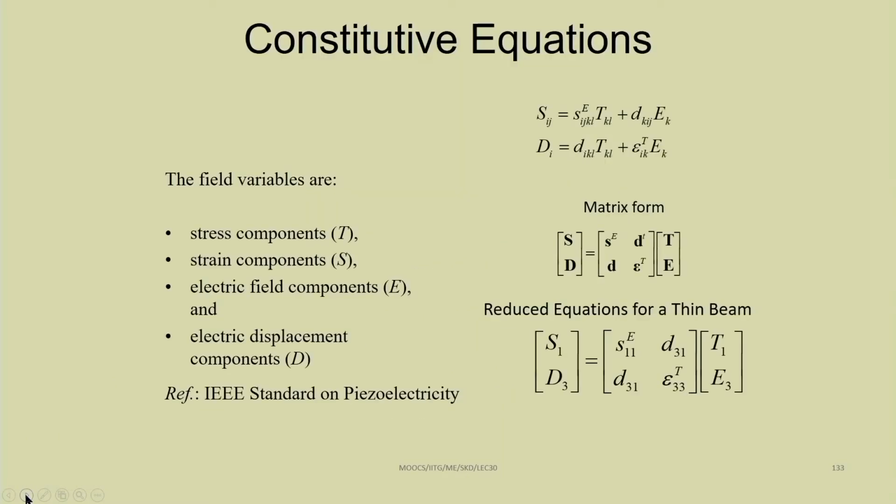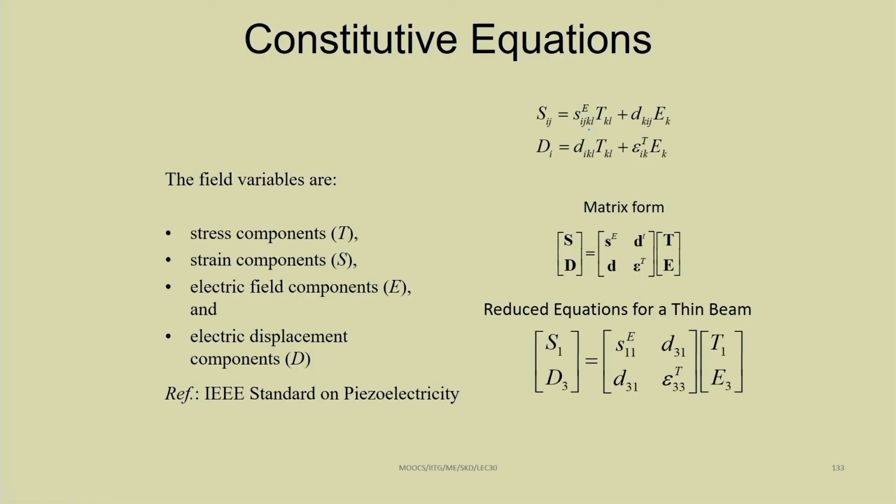While using this piezoelectric patch, we should know that the strain is due to both electric and direct bending of the beam. One part is due to direct bending of the beam and another part is due to the electric part. So, the strain can be written as one part due to the stress component and another due to the electric component.